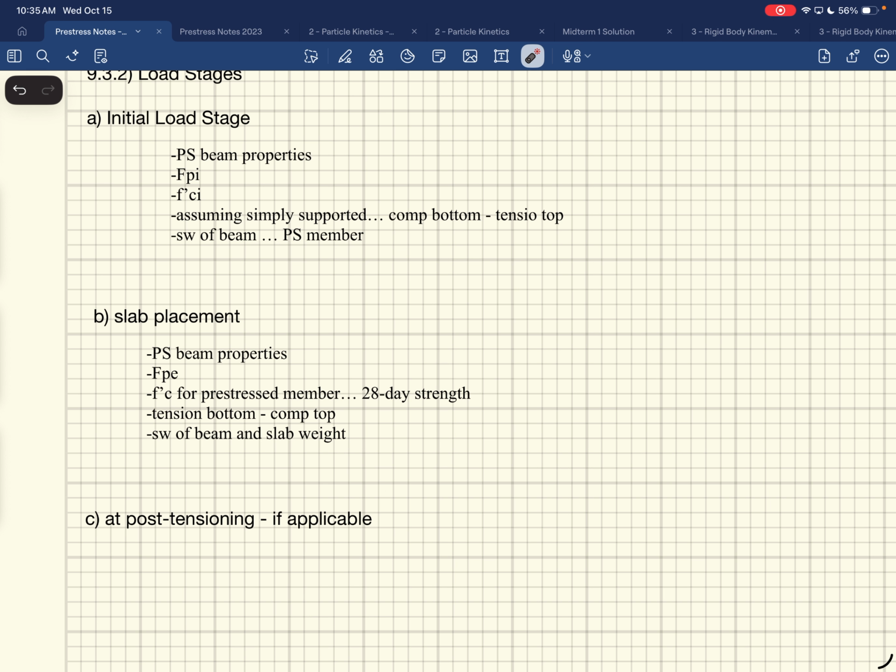The worst case scenario would be no load on it: the initial tension at the top and compression at the bottom. And so really that load on top is just going to help you. It's going to be less. The thing you should be concerned about is if it flips and then starts bending down. But technically you would still have to worry about tension top, compression bottom, but that won't be as bad as the case before. That makes sense, because your pre-stressing force went down and you have the load canceling it out. But you're right, depending on how much pre-stressing you put in there, it could still be popped up.